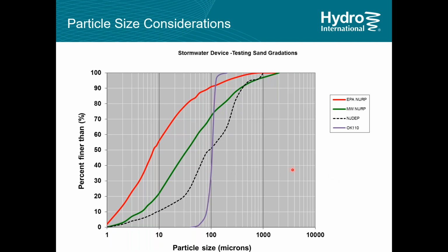If we are looking at removing material, say with a medium particle size, this D50 of less than 10 micron, which we see here in Wisconsin where I live, you really have to use filters, or you got to use ponds or some other system that really can treat very, very fine material. In Minnesota, they use the Midwest NERP curve, and that moves the D50 up to around about 30, 35 microns. Still in the filter range.